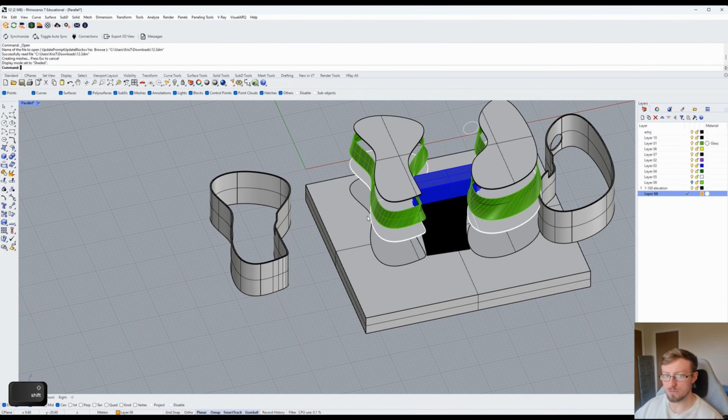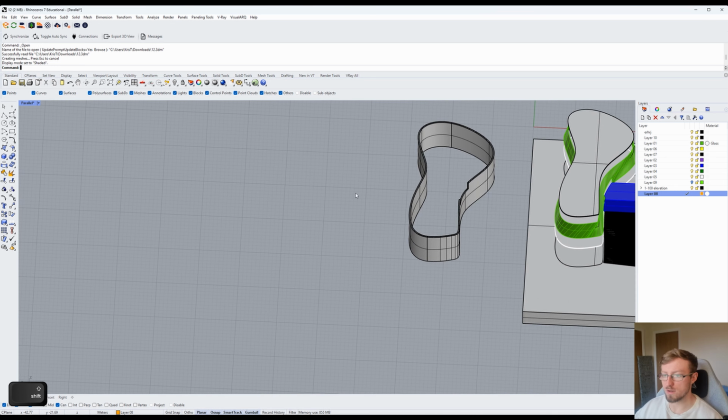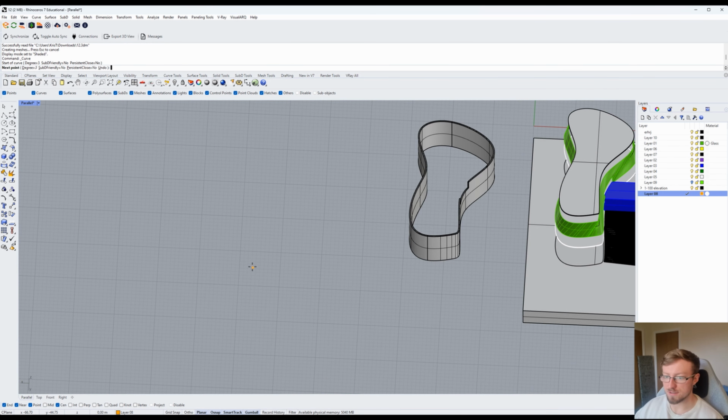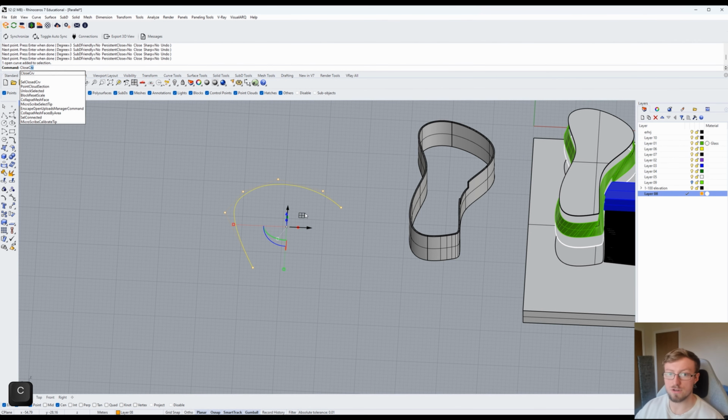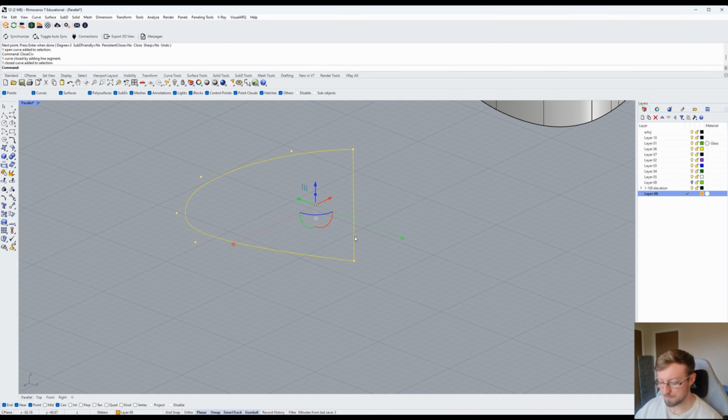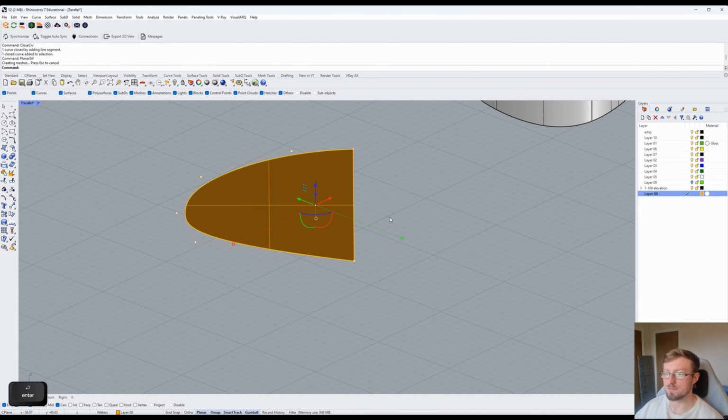Another thing that you can do is you want to close a curve. Say something's open and you don't know where to actually close it. If I just get this spline here, just create whatever. If it's open, you can close curve and it will draw a straight line to do that. So now you could play an array.